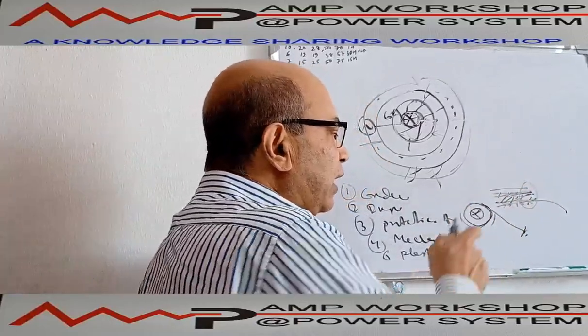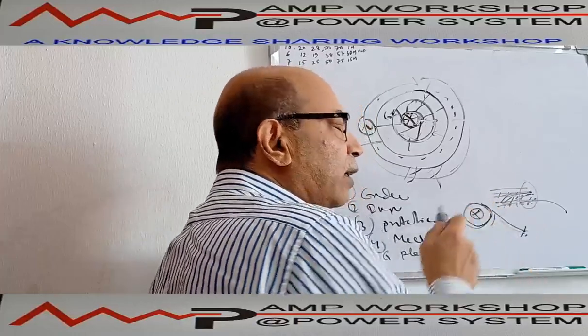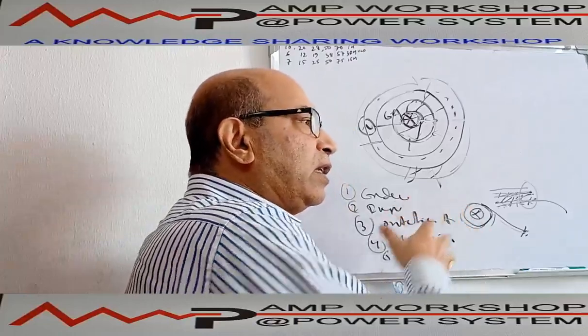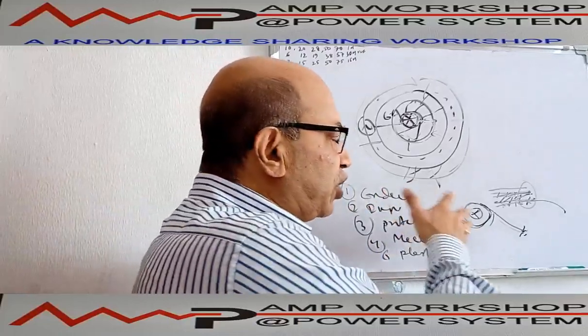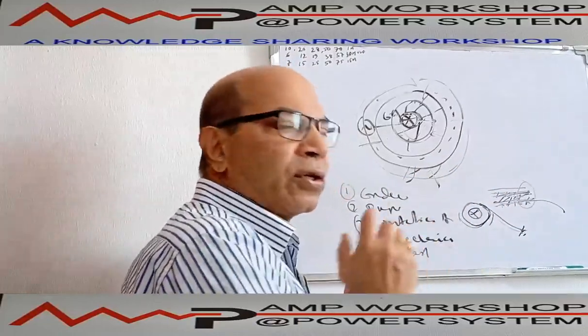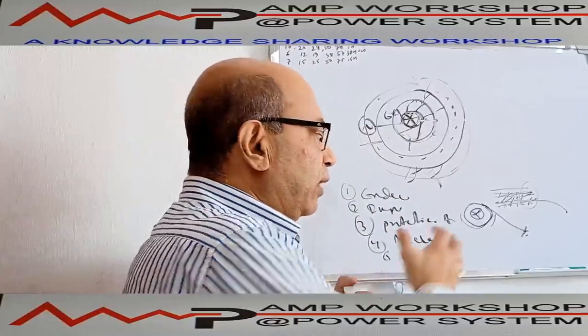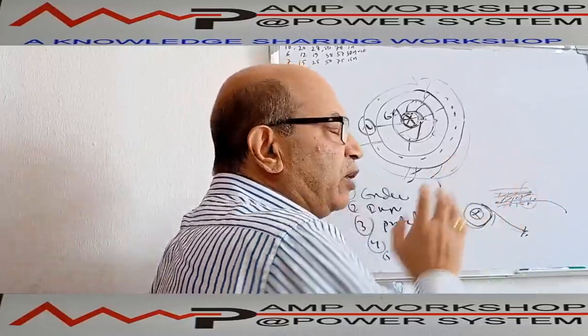So this is called internal sheath wire or internal metallic wire. Over the insulation we can see this thing. This is called a metal tape, to be provided to discharge this accumulation of charges, so that the outer surface will always be at zero potential.